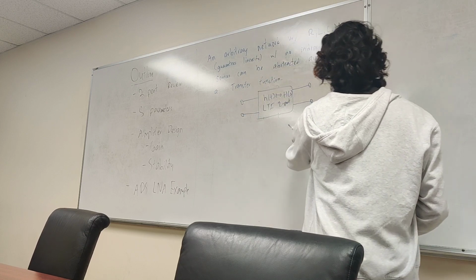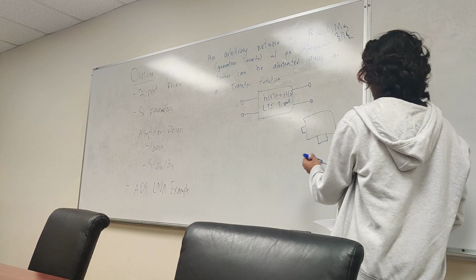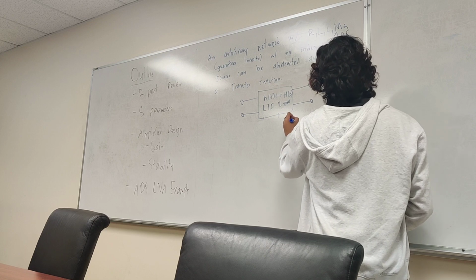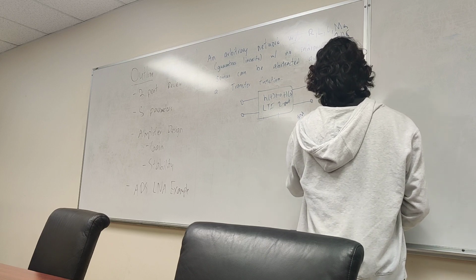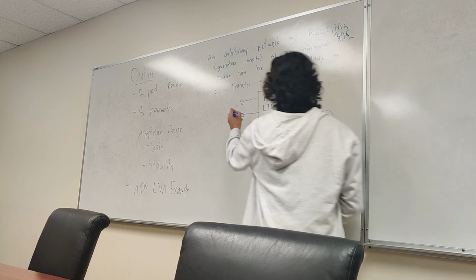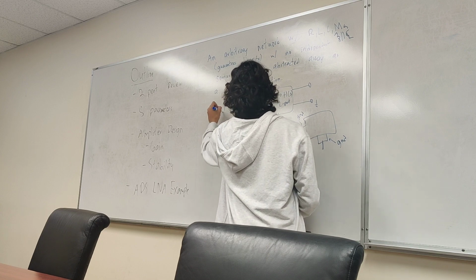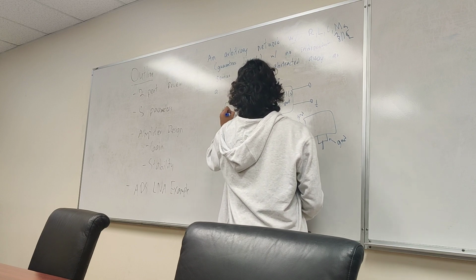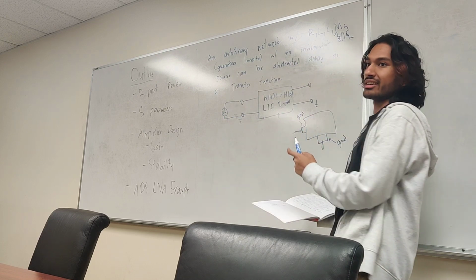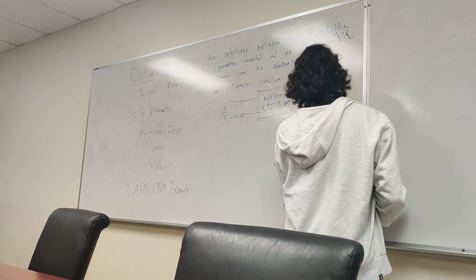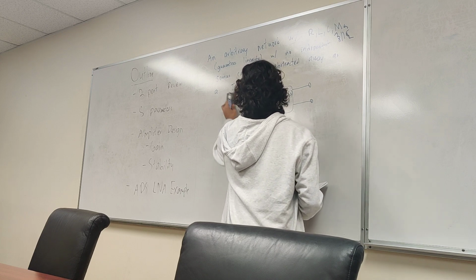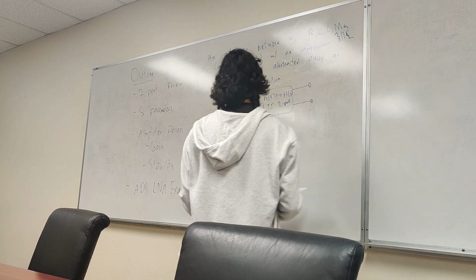And you may ask, okay, well, there's 2 terminals here, right? For our filters, how does that make sense? We have a center conductor, which is our signal path for both, and the outer casing is our ground. So this is our ground. This is our ground. Similarly here, typically you'll have this be connected to ground. And when you attach any external voltage source, it'll just be in reference to this ground here. So you kind of see how that applies. Any questions on that? Cool. So we like 2 ports. We want to work with 2 ports, and when we string them together, we want to have a good understanding of how they operate.